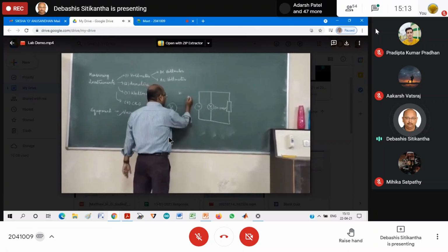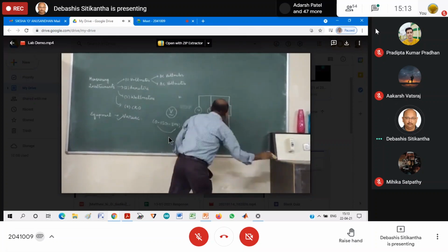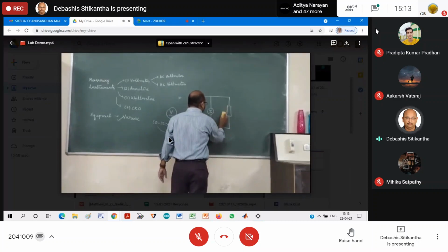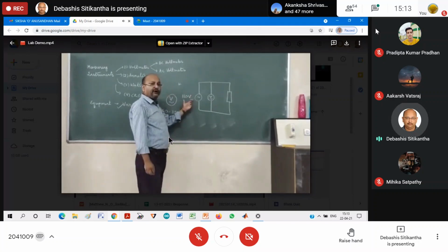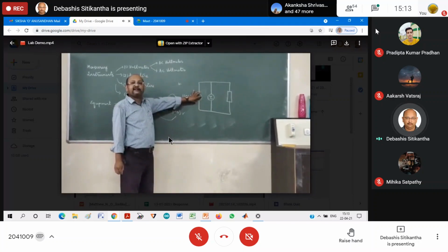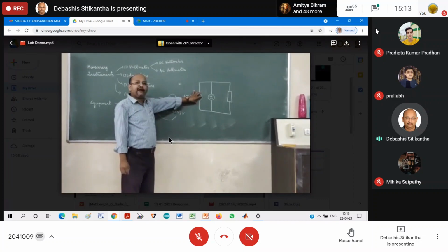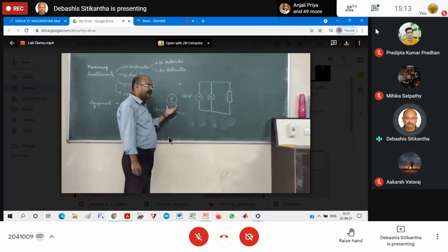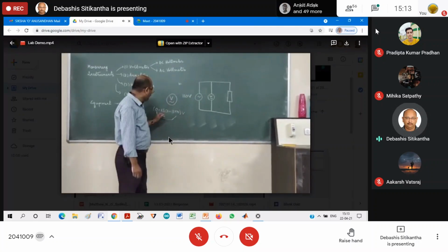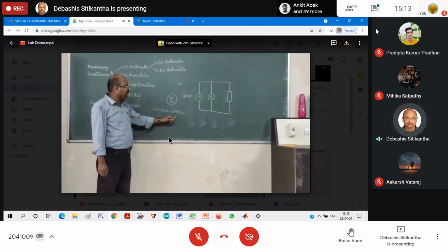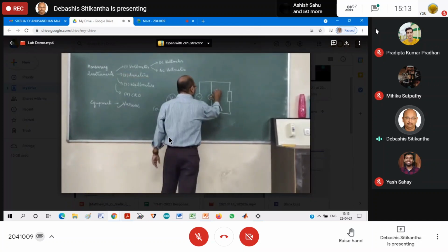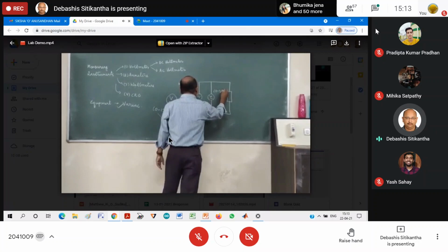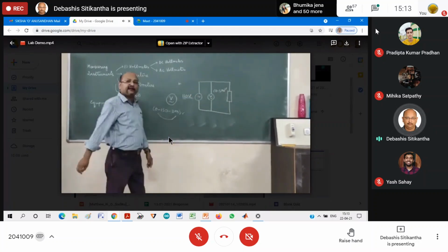Now suppose the voltage produced by this particular source is, let us say, 110, but I don't know the exact voltage across the source, and I need to find it. In this case, I am going to take the same voltmeter with the same maximum range. That means I will connect the voltmeter between 0 to 300. Obviously, it will give me a reading of 110 volt, but with lesser resolution.